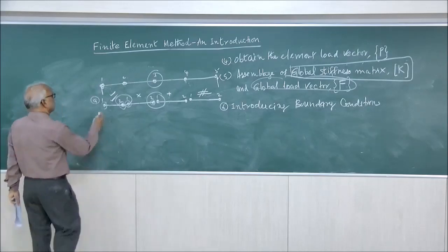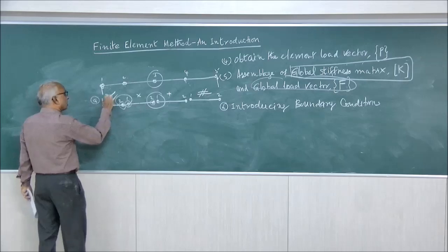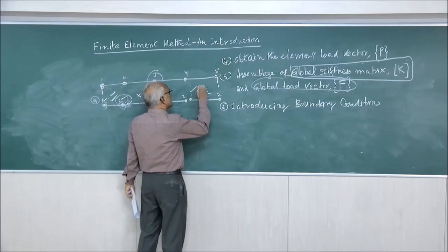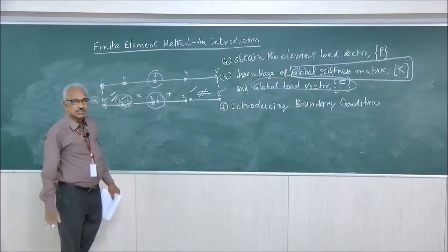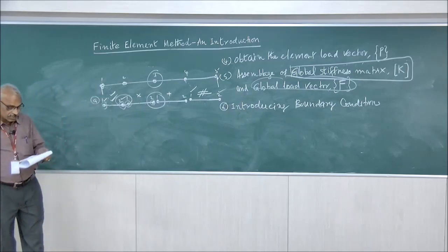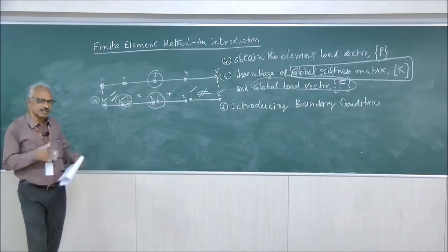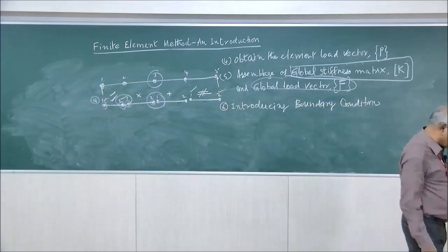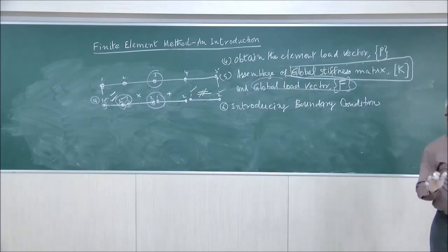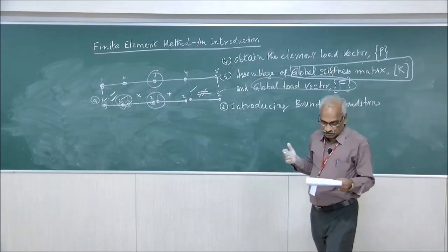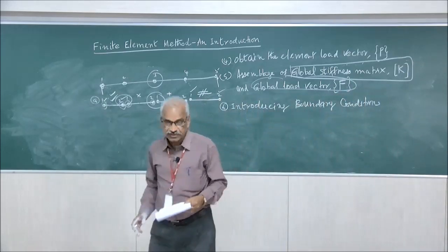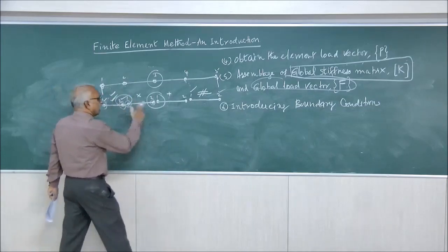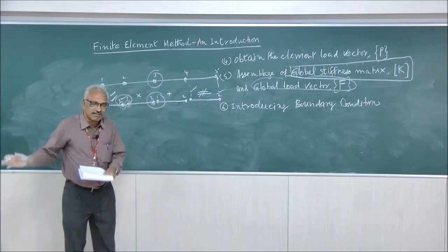When we assumed element number 1, we assumed displacements at node number 1 and node number 2. Similarly, for element number 4 also, we assumed displacements at node number 1 and node number 2. So, as it is, the structure is not grounded, because we have assumed displacements at all points. Before going for the solution, the displacements are to be arrested at a sufficient number of coordinates of the system, so that the structure will be stable. As it is, the structure will have a rigid body motion.